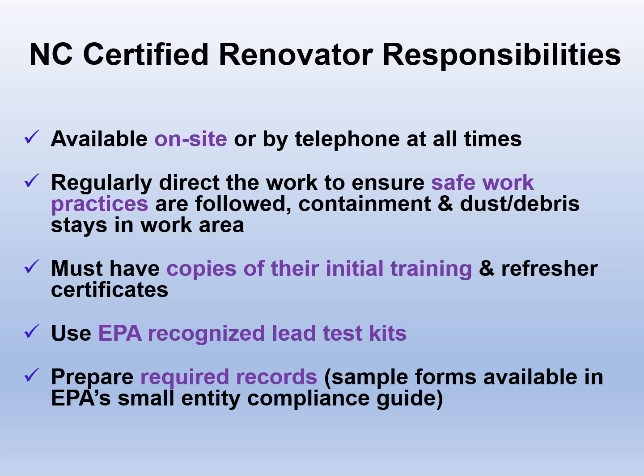Now, we just talked about the firms. What about the individual North Carolina certified renovator requirements themselves? They must be available on site or by telephone at all times. They must regularly direct the work to ensure safe work practices are followed, and containment, dust, and debris stay within the work area. They must have copies of their initial training and refresher certificates on site.